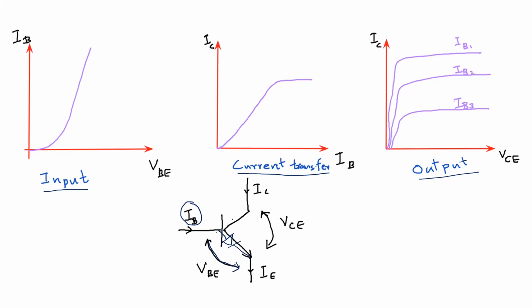So it more or less looks like a VI characteristic curve of junction diode. So the axis are VBE and IB. So we would obtain something like that. And also by extrapolating this one, you can even find the barrier potential. This should be somewhere around 0.7 volts.